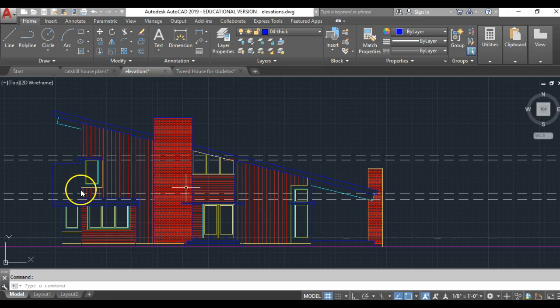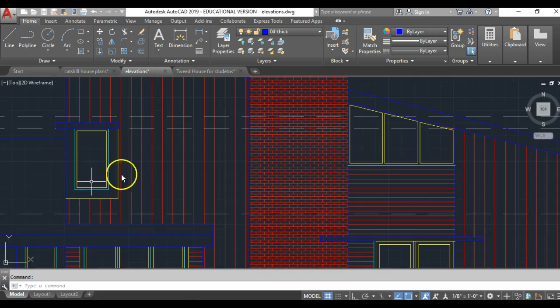So we can see this dark edge on the blue plane, but when I get to windows, which are in the same plane, I step down. The window opening itself is the cyan line. That's the difference between what is essentially on the surface of the wall and what gets pushed back for the window frame itself. And then the yellow here on the outside is trim. It's a minor element, so that's why it's stepped down in line weight, as well as the internal framing element on the inside of that cyan line, the inside yellow line right here where my cursor is. That is also just at that plane, and so it gets the yellow line weight.